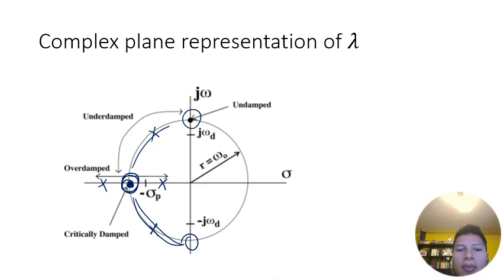And as you change resistance, or the importance of the resistance, you're going to basically go from overdamped to critically damped, then it's going to move towards underdamped, and then eventually we'll get to undamped whenever R is not important. So you should understand this, what people used to call the circle of death, as it might show up in an exam. You should understand what all these symbols mean.